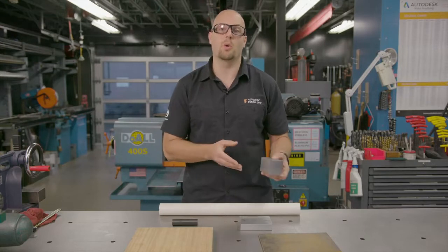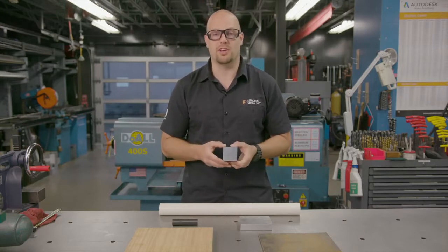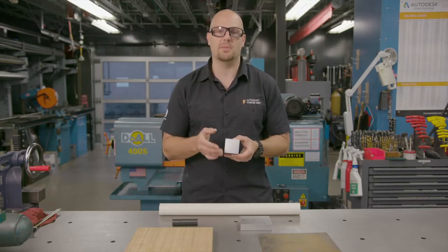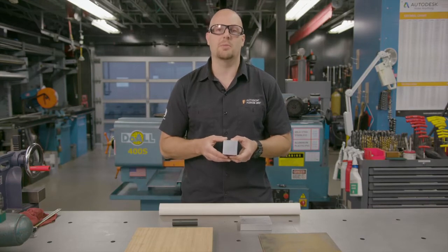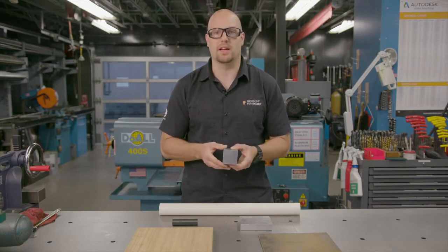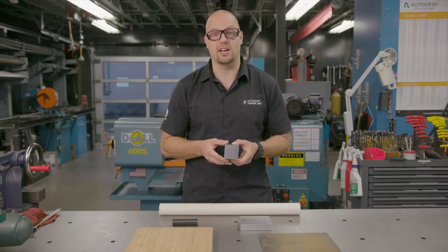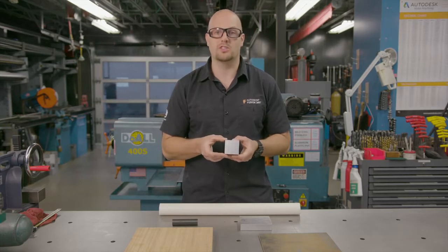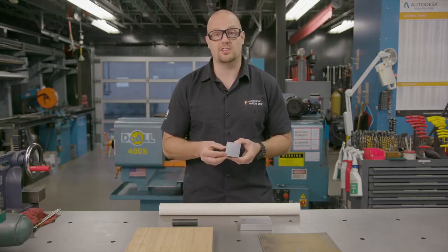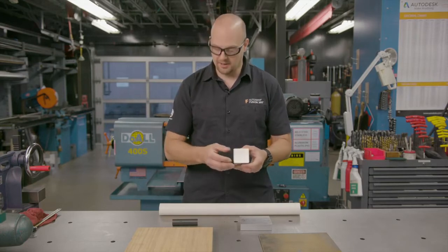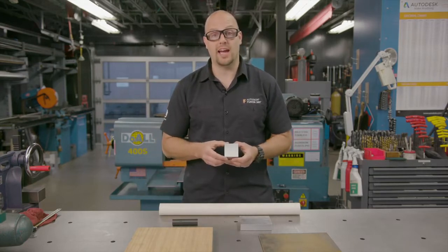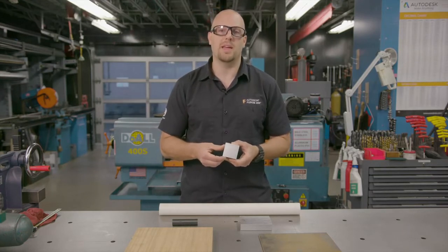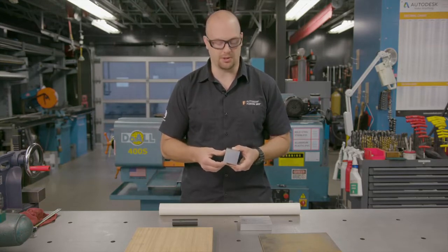Custom sizes, whether you order them or you machine the part down yourself, are going to be more expensive. So if you can design your part to fit inside a piece of standard stock size, you're going to be a lot better off from a procurement perspective than if you needed a custom stock size. With aluminum, for instance, you can get a lot of stock sizes in 1/4 inch increments. You're almost assured to get stock sizes in 1/2 inch increments. Depending on the material, those increments and available sizes of stock will be different. So keep that in mind at the first stages of designing your part.